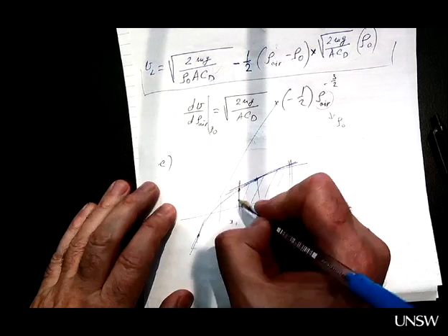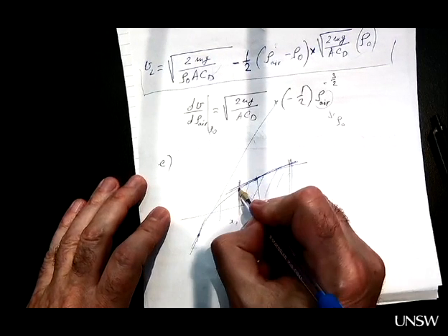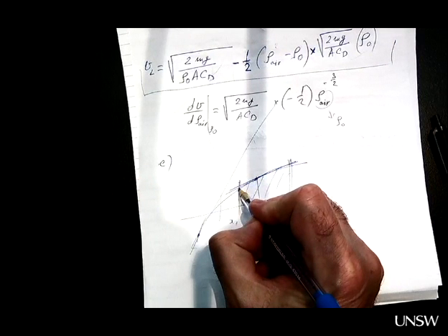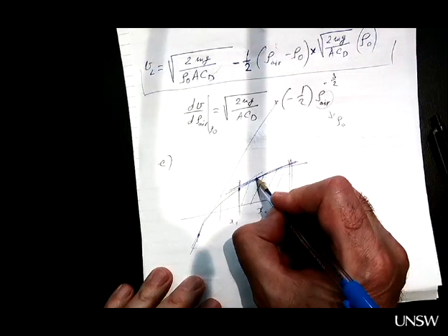In your case, the operating point is the standard sea level density. We didn't say anything about where you are dropping your crate, to which altitude. But in the worst case scenario, if you are dropping on the beach, then the operating point is at the very edge of the operating range, which again is much less accurate than having the operating point somewhere in the middle. So the choice of the operating point here is wrong.